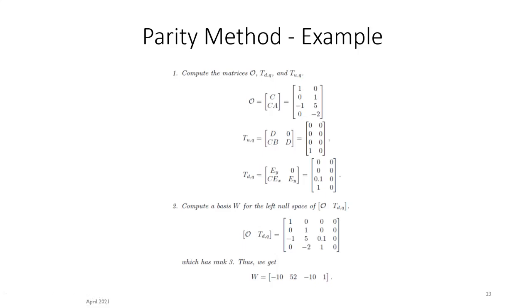In MATLAB you can easily type rank. It's a function in MATLAB: you give it a matrix and it gives you the rank. But when you have a column that is completely 0, it means that the determinant of this matrix is 0. And when the determinant of a 4 by 4 matrix is 0, the rank is not 4. It doesn't matter if you don't remember from mathematics why the rank is 3; I'm telling you that the rank is 3. And because the rank is 3, we don't need to differentiate anymore. It is not full rank.